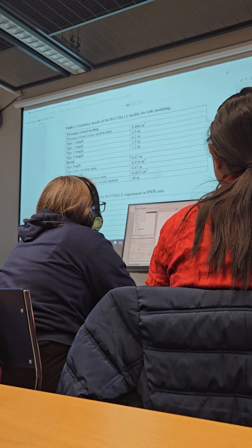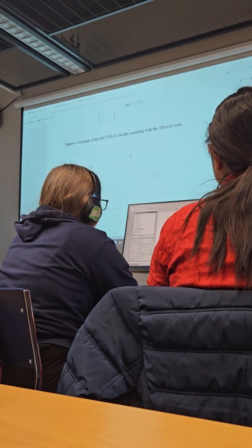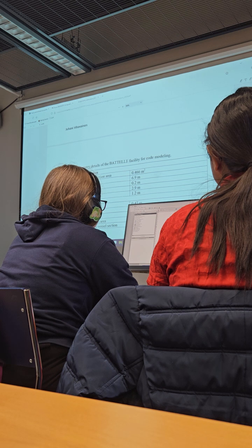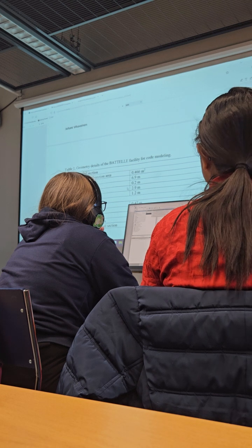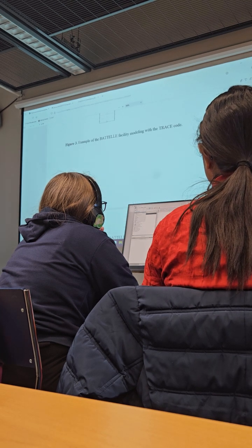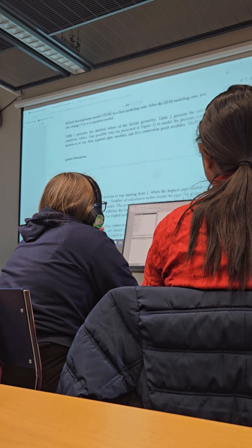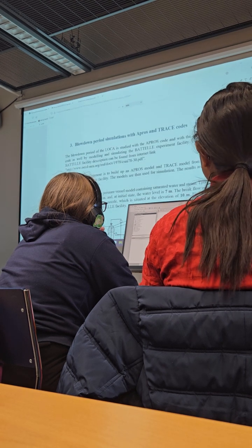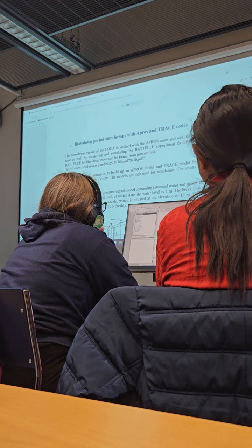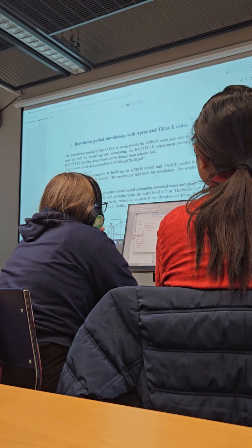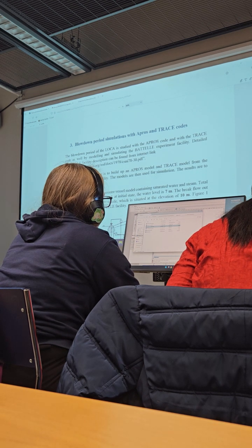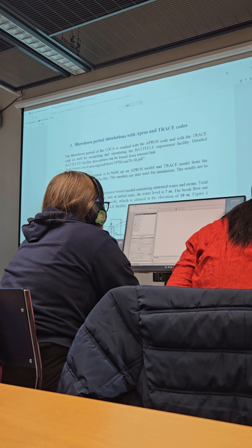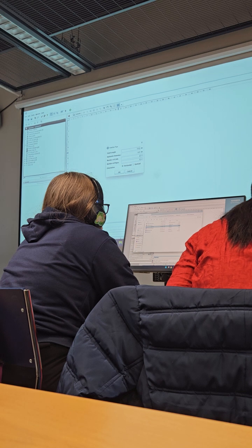These pipes 1, 2, 3, and 4 are made for the APROS approach, but we knew that the whole facility was given the values of height of 11.2 meters, and then the water level should be set to 7 meters, and then this horizontal pipe should be attached at the level of 10 meters. So these are the tricky points that we should take care of.